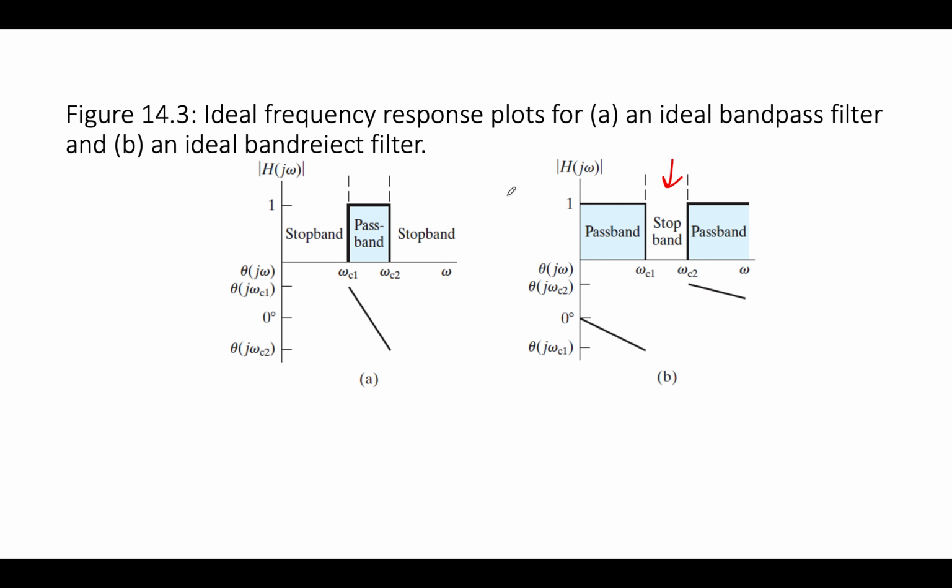So once again, all of these filters illustrated here are ideal. We most often look at the magnitude when we're just trying to get an intuitive feel. When you get to actually looking at communications and information transmission, suddenly the phase becomes extremely important because you're often doing something to the signal and then regenerating it. So at that point, phase information is also particularly important. But a lot of times people look at a phase curve and this doesn't mean anything intuitive, so they look at instead at the magnitude curve.